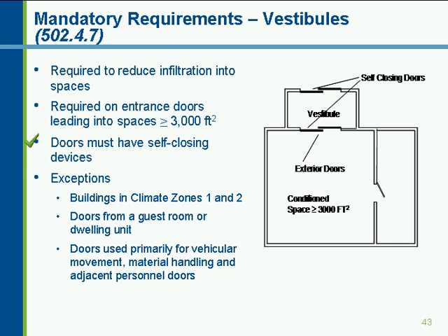If you have an entrance into that, and we show an entrance into this particular space, if there's a door on that entrance, I would not count the square footage on the other side of that door as part of the conditioned space. If there's no door on that entrance, or that opening between what might be a less than 3,000 square foot space and the space next to it, I would go ahead and count that because you will have heat transfer between the two spaces.